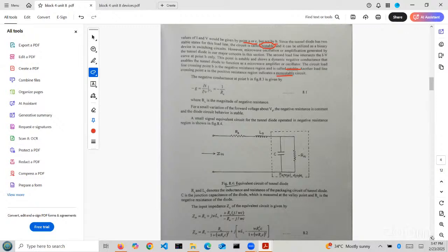Next here, what am I doing? Taking resistor, inductor, and capacitor combination. Here, one capacitor, and here current is decreasing in negative. Do you remember the current is decreasing in the negative resistance region? So here the resistor which I am taking is which resistor? Minus Rn. Why did we keep the minus sign? Because it is a negative resistance region. So the negative resistance and the capacitor, are both connected in series or parallel combination? Both are connected in parallel combination. This parallel combination is treated as a tunnel diode.